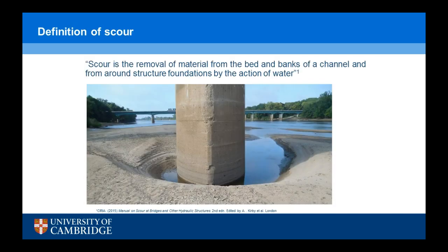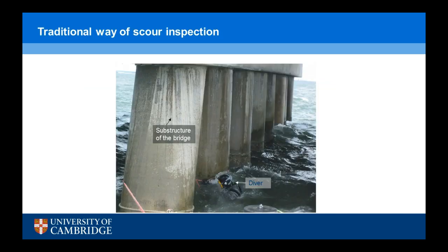For those who are not familiar with scour, let me give you a brief introduction. Scour is the removal of material from around a bridge foundation because of the fast flowing nature of water. Especially during flooding, when so many eddies are created, there can be erosion around the bridge foundations, which can lead to bridge failures.